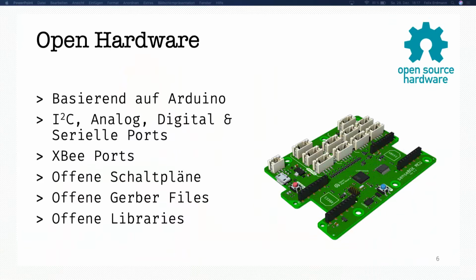All this is based, like I said before, on open hardware. We've developed our own module based on Arduino. It's the senseBox MCU, and the reason why we've done that is because we started with the Arduino Uno, and you couldn't use all sensors at the same time and upload the code. The memory capacity wasn't high enough, so therefore we added this module and modified it.